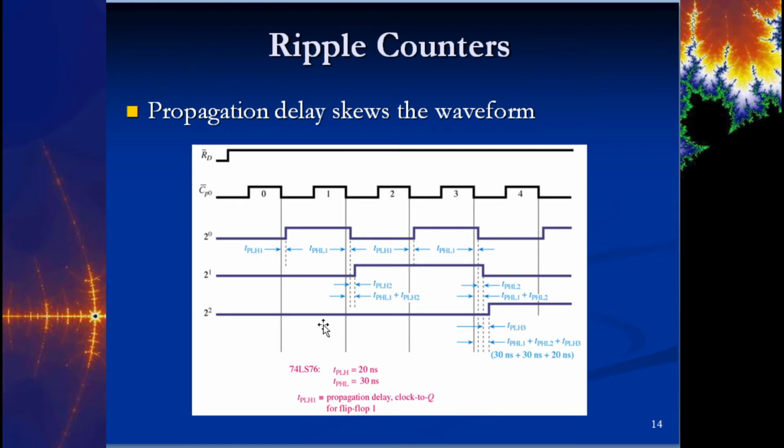And if you remember from our discussion, we call that the propagation delay. So inherently, just by using a flip-flop, there's going to be a tiny little delay there. Now they're saying that the low to high propagation delay, in other words this case right here, is a low to high. This would be a high to low transition. So one of them is quicker, one of them is slower. It takes longer to discharge as opposed to charging, apparently. So 20 nanoseconds here, and that's already built into this.